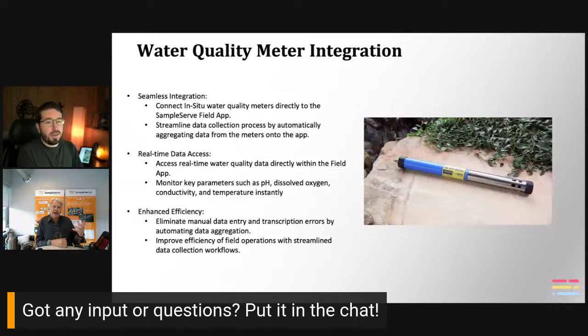So that kind of automation, being able to pull that data out, and there are audible alarms. Every time it's going to take a new reading, it gives you an alarm. And when you're stable, based on a US EPA protocol, it gives you a different alarm, a little louder, a little longer, so you'll know that's ready to sample. It continues to operate and record data until you go over there and hit the sample button, and it does a timestamp and records all that data. And then it's all documented for you too.